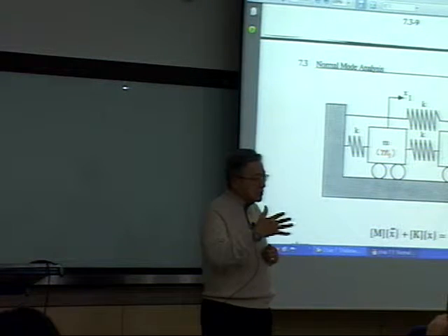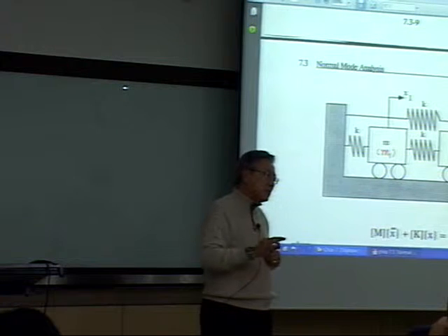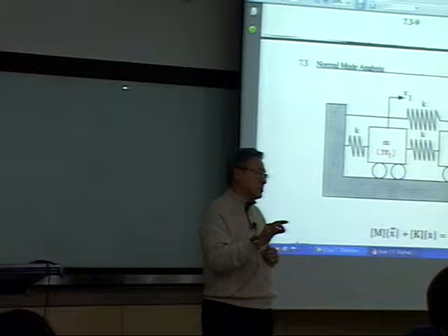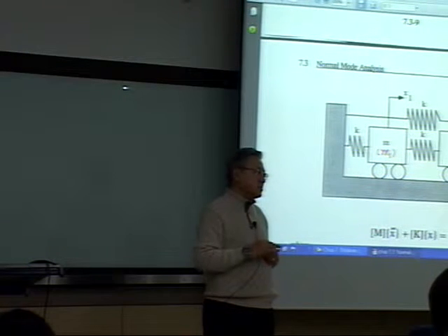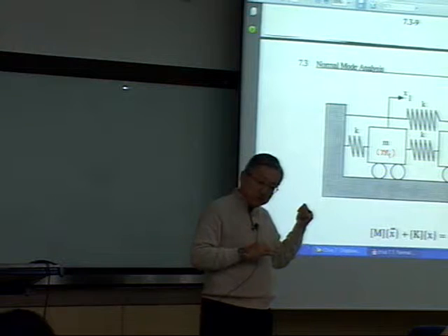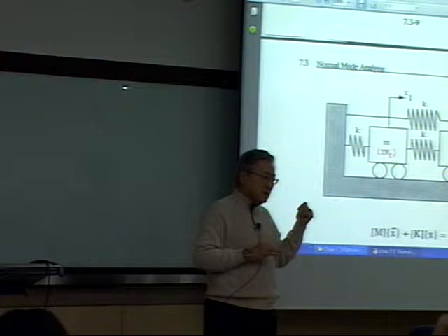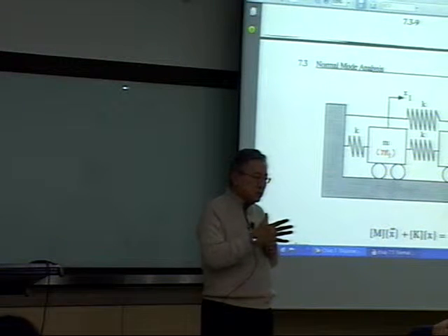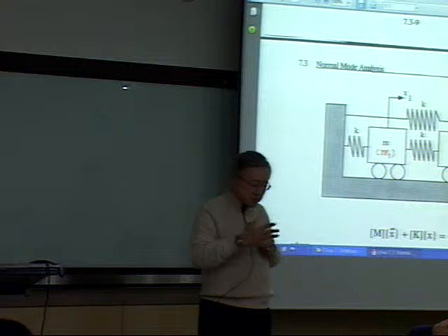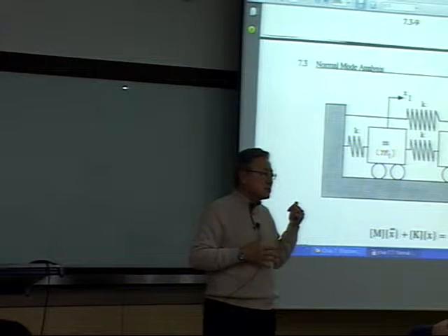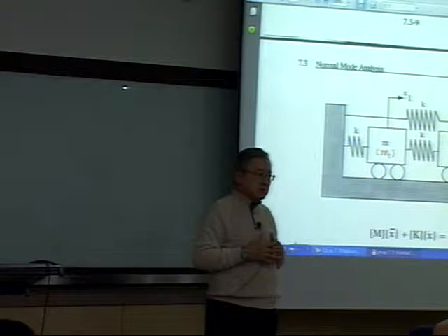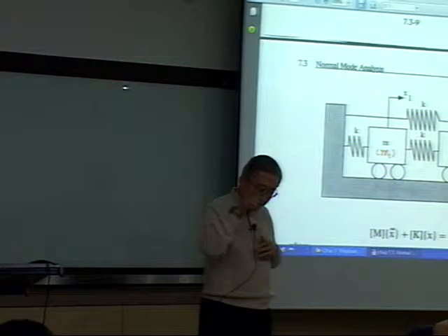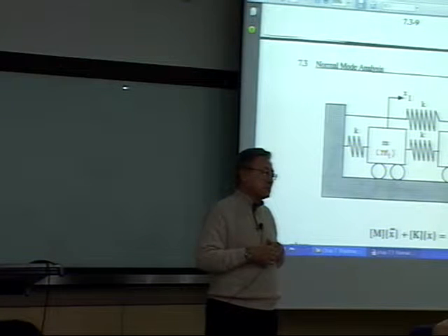So to define the motion of any node, any point, or any particle in space, you need 6 degrees of freedom. But this particular system is planar, and the motion is constrained in all other directions except the horizontal direction, so you need 2 independent coordinates to define the motion, drawn at mass 1 and mass 2.